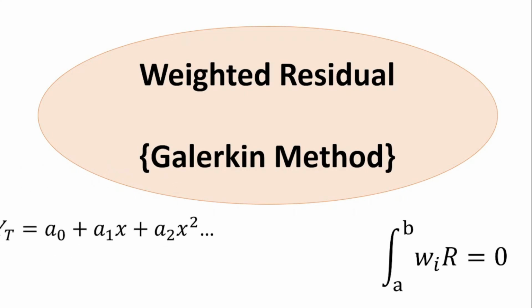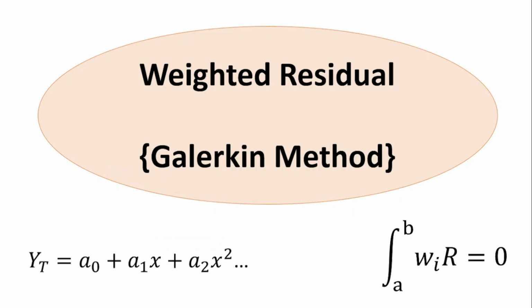So we're going to look at an example quickly, but before then I want us to note that our trial function is key in finite element analysis. It's also something we need to know. A trial function is just a polynomial equation, usually a0 plus a1x plus a2x squared plus a3x cubed plus a4x to the power 4 plus a5x to the power 5 up to an x to the power n. But usually you truncate at any point. You can use only a0 plus a1x plus a2x squared. Some other person can say, no, let's add the other two terms, a3x cubed plus a4x to the power 4. Some other person, so it depends.